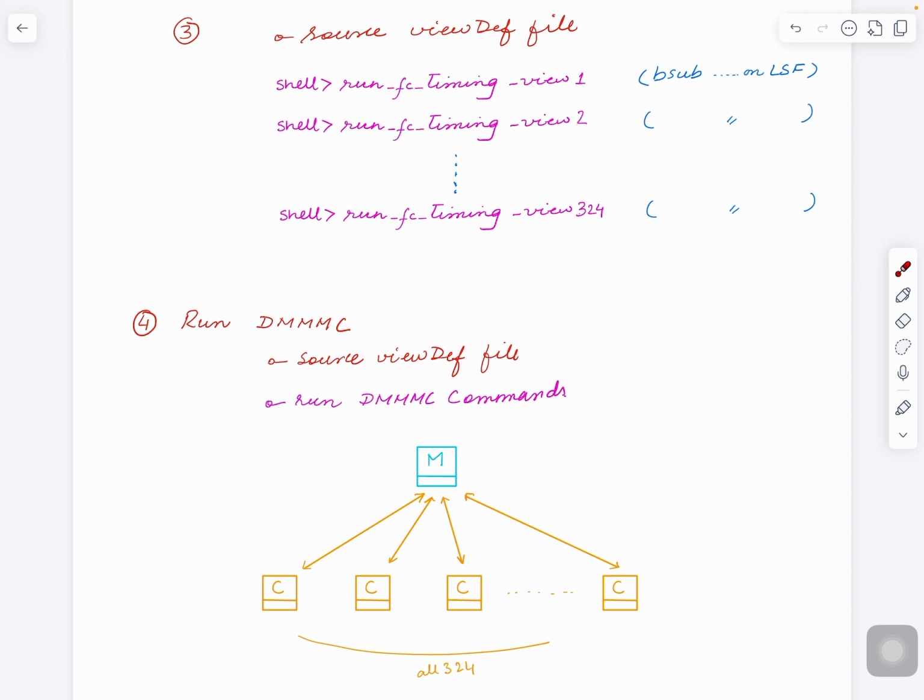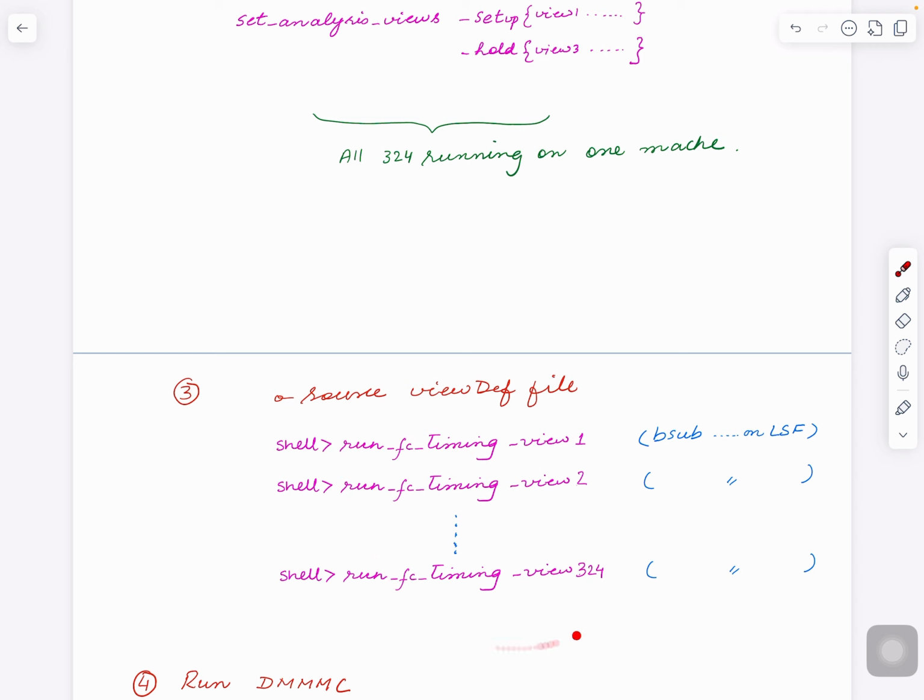Keep in mind, this is different from, for example in the case of Tempest, the distributed STA. That is different because that's where you're partitioning the design into multiple versions so that eventually you can run smaller jobs. These ones are still running pretty heavy, pretty big, and they need bigger machines in this case. Some people don't like it because the implications can be that one of them crashes. So what happens in the pulling up? I don't remember the full flow, but so far this is the more widely used scenario that I've seen in the industry.